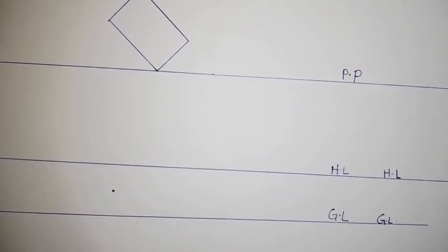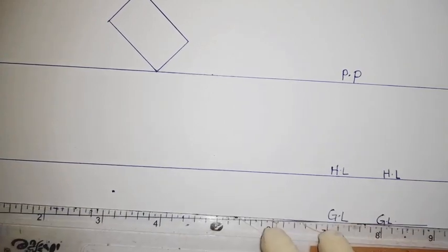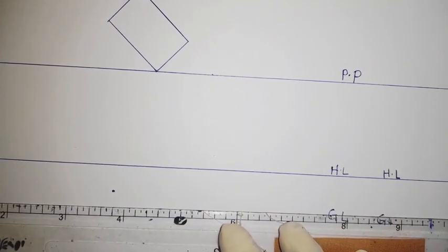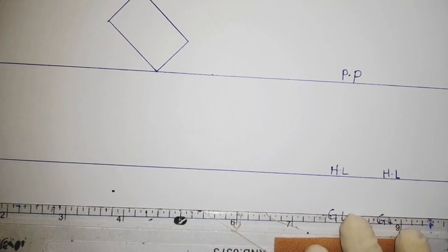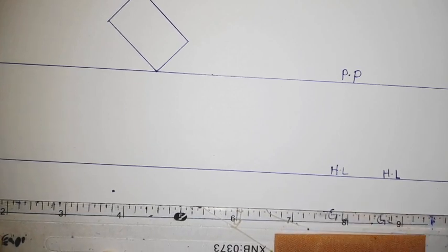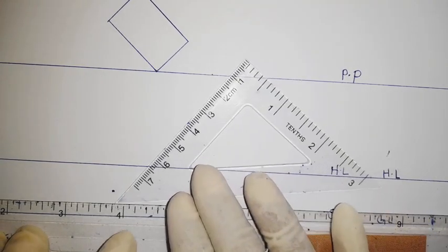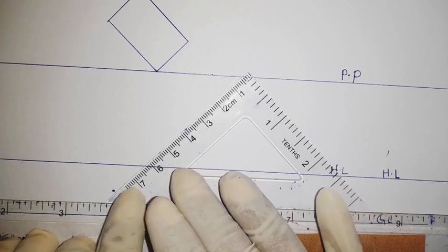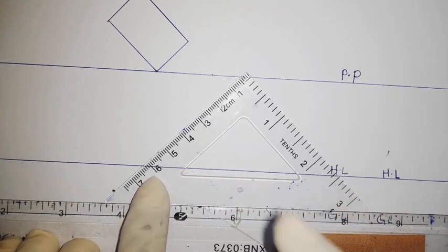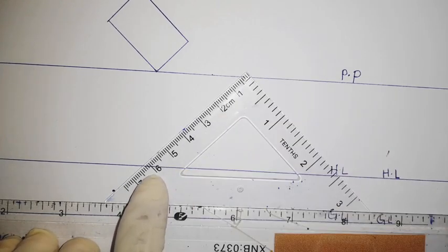So for our procedure here, first of all, we shall draw lines from the station point that are parallel to the 45 degree planes of our block. We draw parallel lines. They are not 90 degrees, but 45 degrees. So from here, we expect to draw a line from the station point going this direction to meet this picture plane.